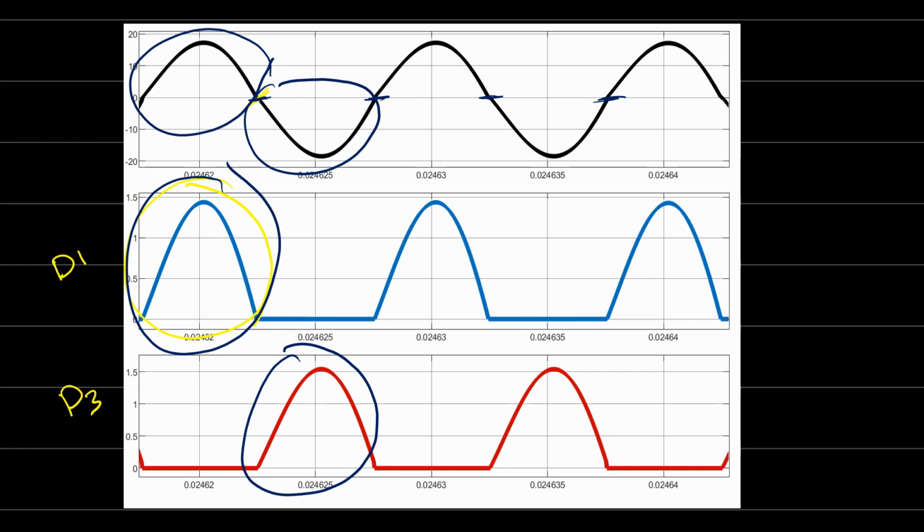The conduction losses and switching losses will be minimum. Why? Because we operate at resonant frequency, and life is easy. Okay, you can pick different frequencies, for example, if you want to design a different application, like different input voltage, different output voltage.